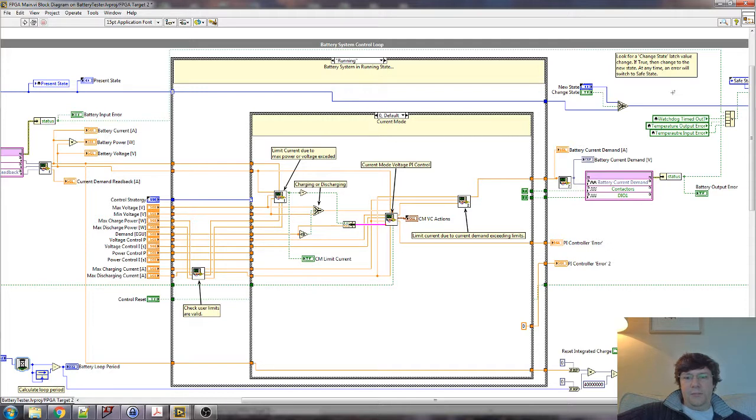You put your professional driver in the electric vehicle of your choice, and you put some stuff like a dSPACE MicroAutoBox or some NI kit in the boot or under the floor or wherever you can find a bit of room, and you get into the CAN bus and record everything you can get your hands on. Throttle positions, gear, engine revs, whether the heaters are on or not, battery voltage and current, contactor positions. Everything that goes down the CAN bus, you take the log and pick through it afterwards. And you retire to your laboratory with your battery, your bespoke battery tester and this data.